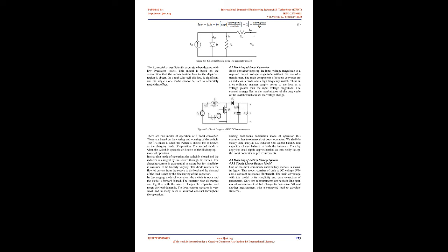2.4 Photovoltaic Array. Desired power, voltage, and current can be obtained by connecting individual PV modules in series and parallel combinations, in much the same way as batteries. When modules are fixed together in a single mount they are called a panel, and when two or more panels are used together, they are called an array. Single panels are also called arrays.